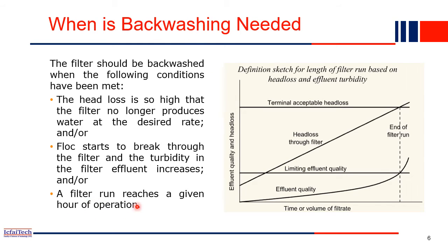And third, the filter run reaches a given hour of operation, like 24 hours, or maybe 1 week, depending on the design of the filter medium. When it reaches the end of this time, then you have to do the backwashing.